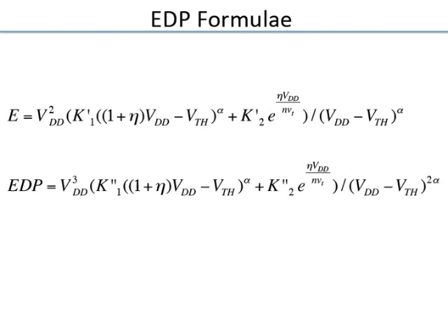These kinds of analytical formulae are very useful. Of course, there is a certain simplifying model you use, and then there are certain constants like K1, K1 dash, etc., which you fit. You take the actual circuit, do a few simulations, and get these parameters, and then you fit it and get this characterization of your circuit, which you can then use to figure out the right setting for some of these parameters. The analytical formula allows you to get to your answer quickly, and there is a certain insight you can get.